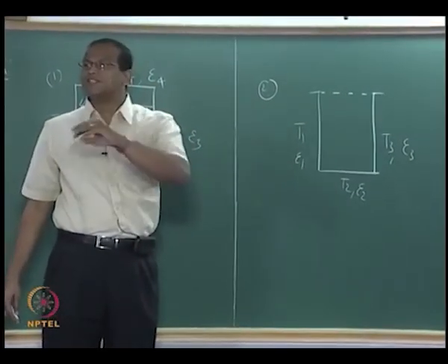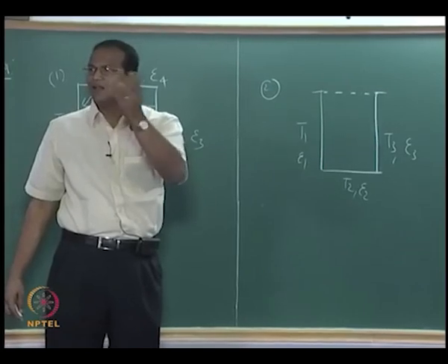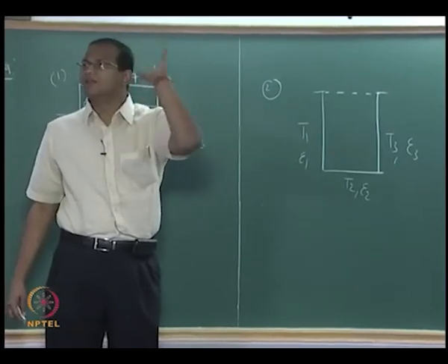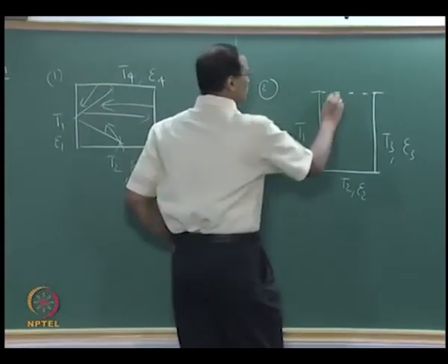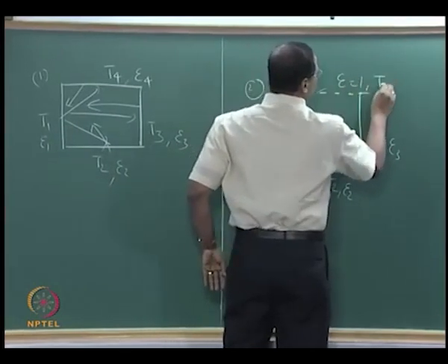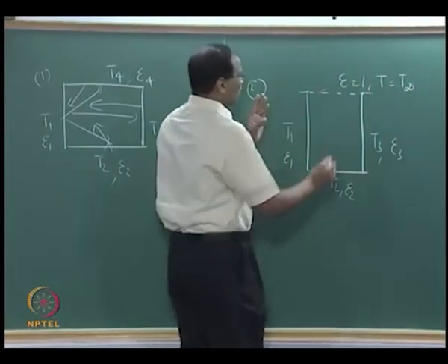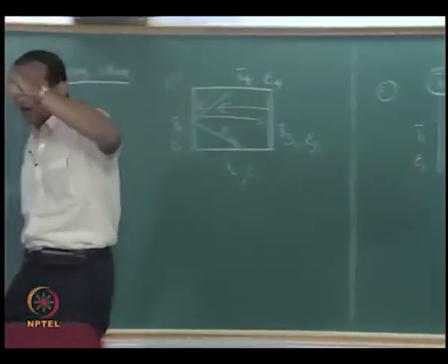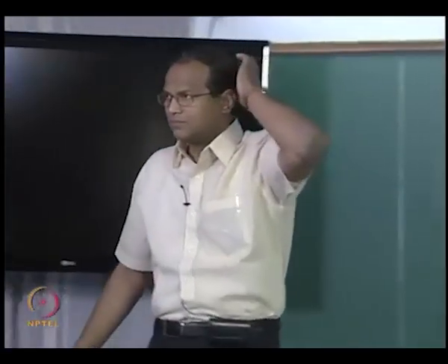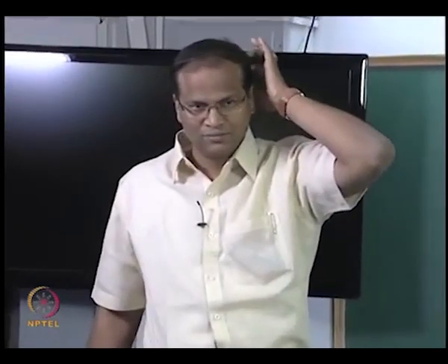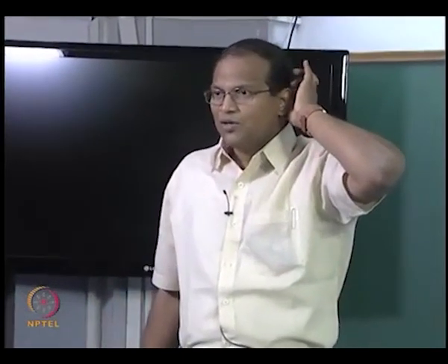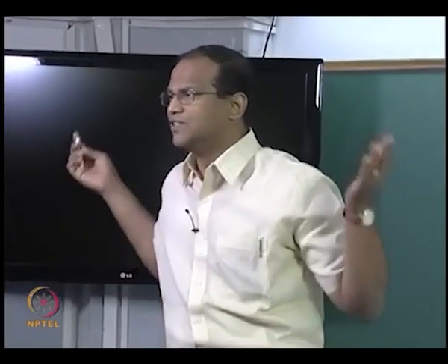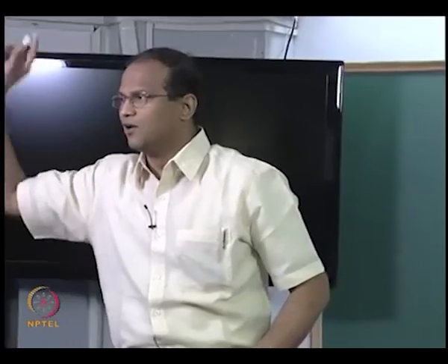That imaginary surface has 0 reflectivity, that is, it is a perfect emitter and has a temperature equal to T infinity. Okay. So, that is the beauty. So, I consider it as the 4th surface. Now, I also treat it as an enclosure. Any possible configuration on this planet Earth can be treated as an enclosure. If the surface is open, put a dotted line and close the surface.